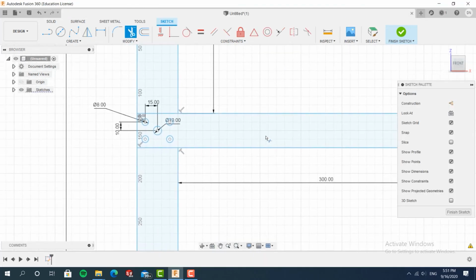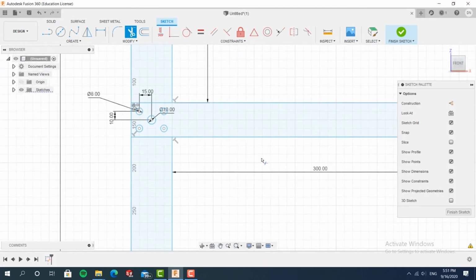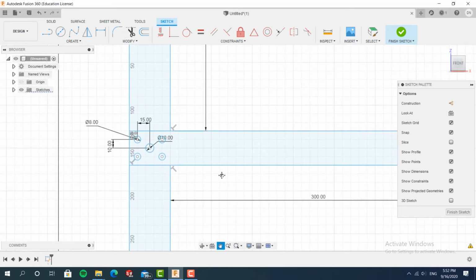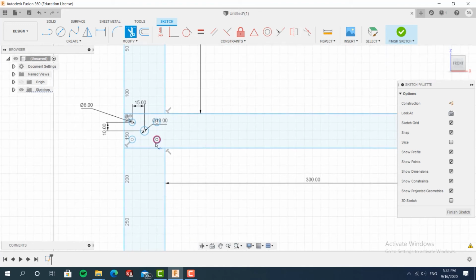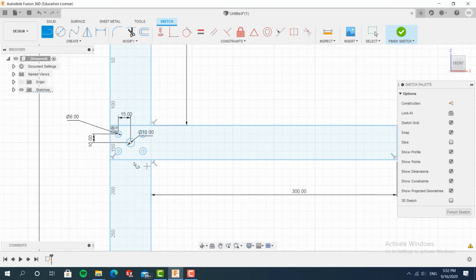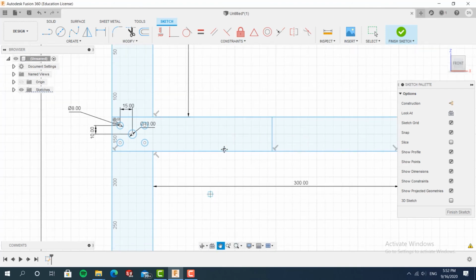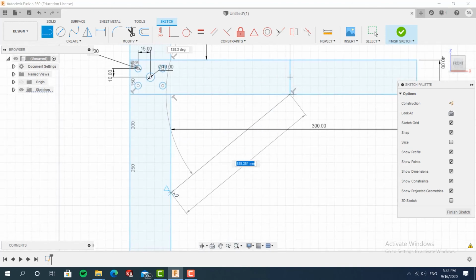Next, after you're done with pocketing, you also have the concern of durability. Of course, there are going to be parts that will receive significantly more stress than others, since not every part supports the same amount of things, and not every part moves around in your system. So for support, just support the parts that are connected to the base because they will bear a lot of load. They basically need to carry the whole weight of your robot.